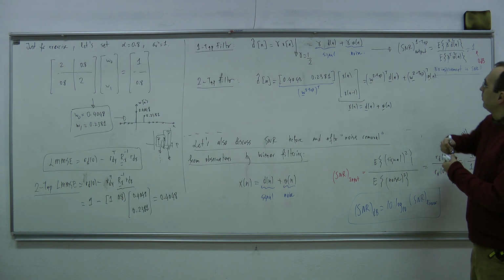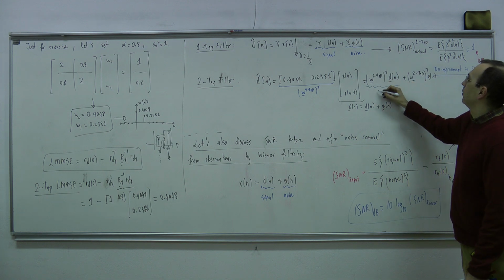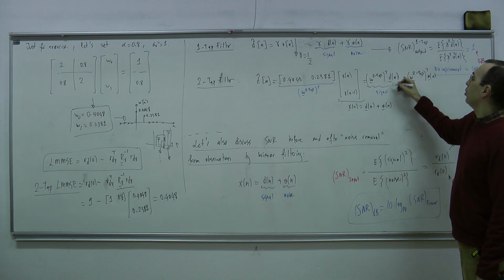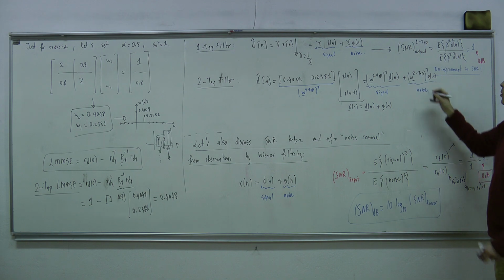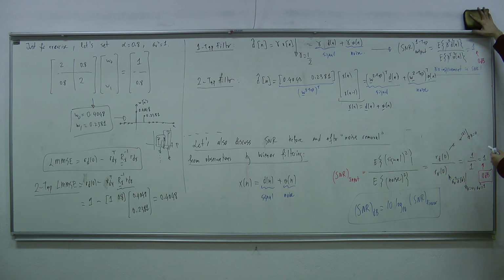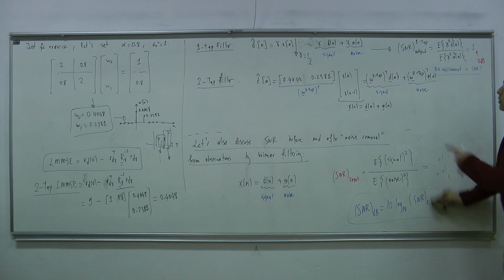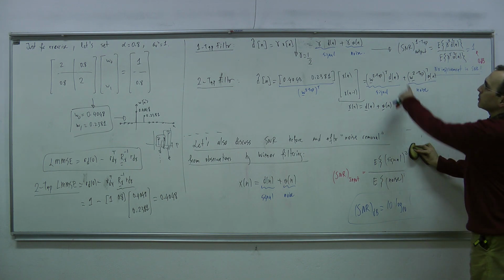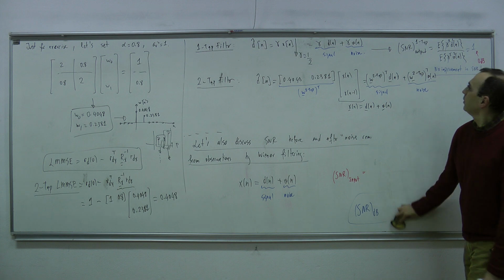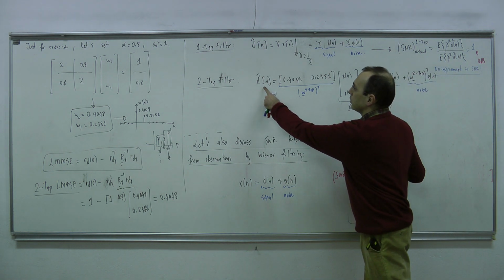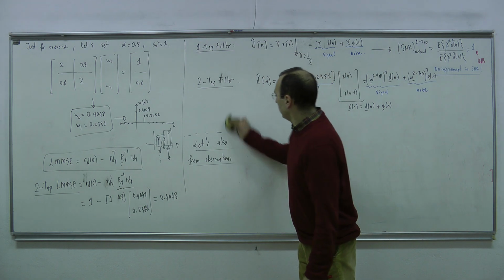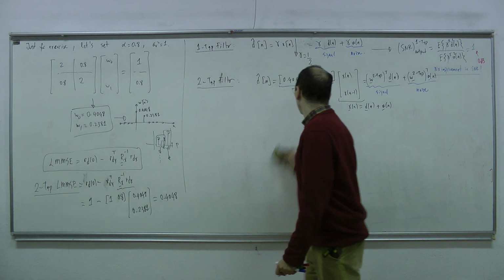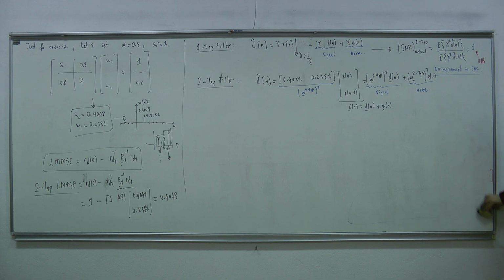Well, I will call this thing my signal because it contains all of these d terms. This is my output noise. Okay, I have that. So can I calculate the power of this? This is a scalar actually, isn't it? This is just a scalar because this is the output at the end time of that filter. So I should be able to calculate the second power of that scalar and take its expected value.